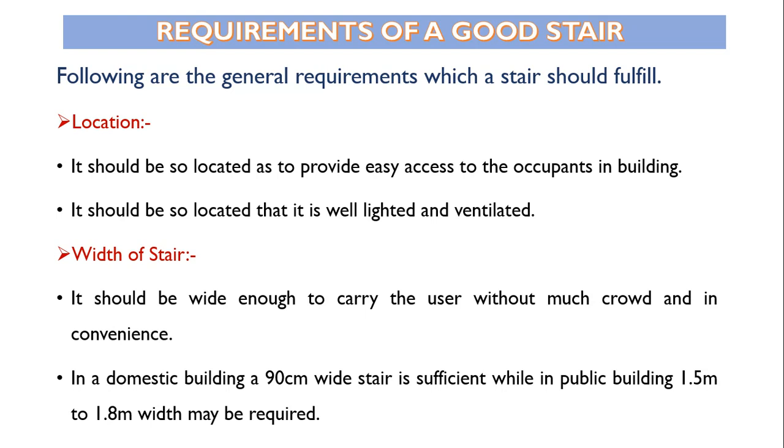Then the width of the stair. It should be wide enough to carry the users without much crowd and inconvenience. In a domestic building, a 90 centimeter wide stair is sufficient. So the minimum width of the stair in a residential building is 90 centimeter, that is 0.9 meter, and in a public building, the minimum is 1.5 meter. One can go up to 1.8 meter depending upon the requirements. So this is regarding the width of the stair.